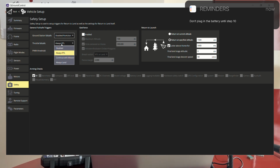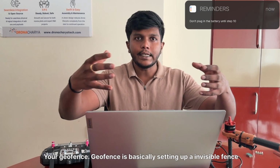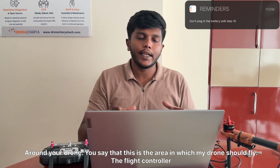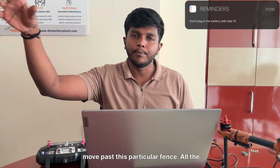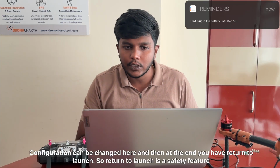And then you have your geofence. Geofence is basically setting up an invisible fence around your drone. You say that this is the area in which my drone should fly. The flight controller along with the GPS won't allow your drone to move past this particular fence. All the configuration can be changed here.